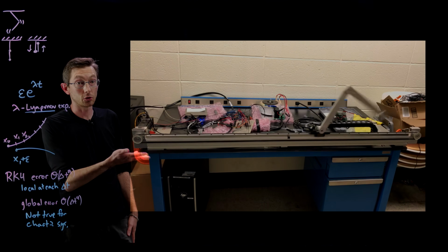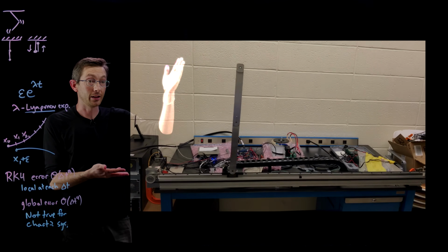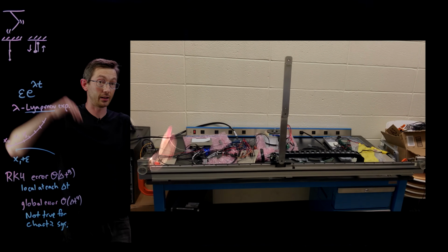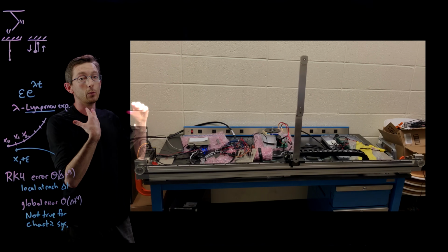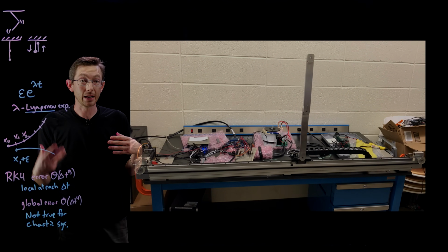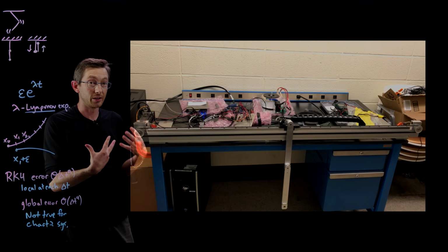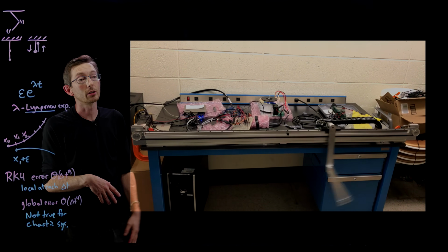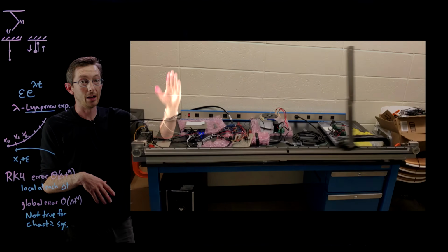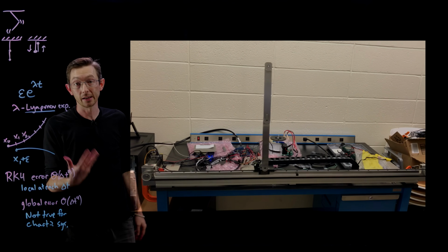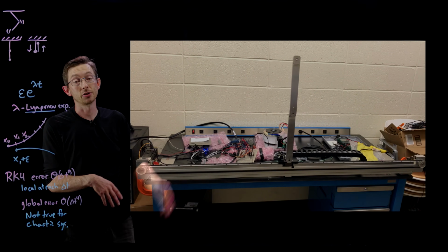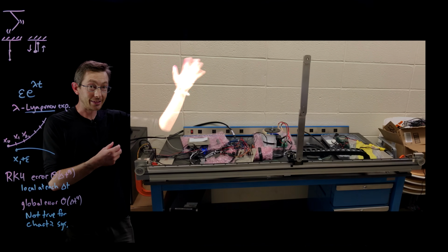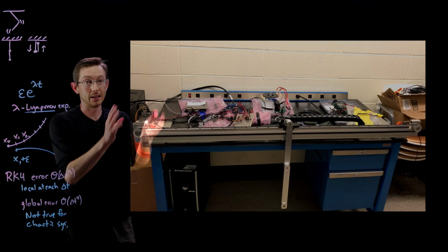So you can control a chaotic system. We've pumped in a lot of energy, so it's well above the chaotic threshold. But with feedback control and with a good enough integration scheme, a good enough model predictive controller, we can actually swing this pendulum up and stabilize a condition that's normally unstable, and definitely with enough energy that you would classify it as chaotic if I let the system go.